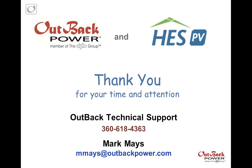Yeah, it's an education issue. We're going through this with Southern Cal Edison as well, and they just don't understand. One of the local utilities here, Puget Sound Energy, came up with some metering schemes. There's a 3-meter scheme that they use for what they call Outback inverters, and it's an A plus B minus C metering scheme where any energy going into the battery will always get subtracted out. So there is a way you can meter it to make sure you're not doing a generator or something. But again, it's an education thing. I'm not sure we're there yet, but there's no reason why we couldn't do it technically speaking; policy-wise, we still need to get that worked out.